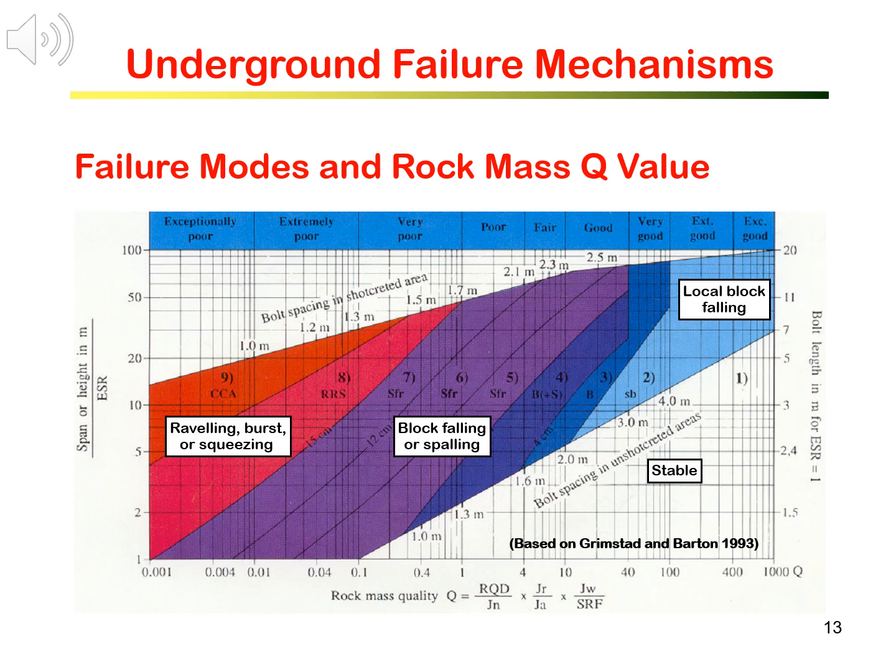The stable zone is shown on the lower right, and the unstable zone or possible collapsing zone is on the upper left. Here, different failures and the support to stabilize the potential failure are quantified by rock mass quality Q and excavation dimension.